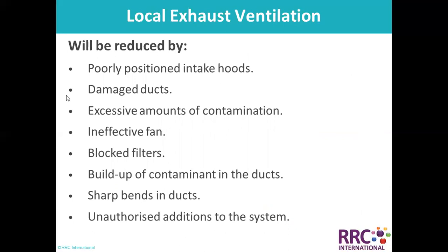How are we going to reduce it? Poorly positioned intake hoods, damaged ducts, excessive amounts of contamination, ineffective fan, blocked filters, buildup of contaminant in the ducts, sharp bends in the duct, or unauthorized additions to the system. So yes, ventilation will definitely be affected, or we can improve if we can avoid all these issues, which is not easy, by the way, because normally our maintenance teams sometimes don't take everything seriously. They always believe, oh, this is acceptable. This safety gentleman is always behind us.